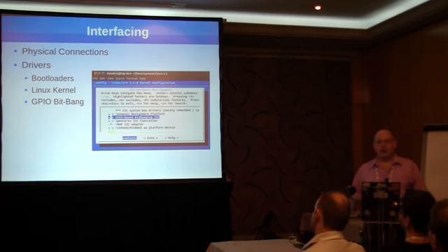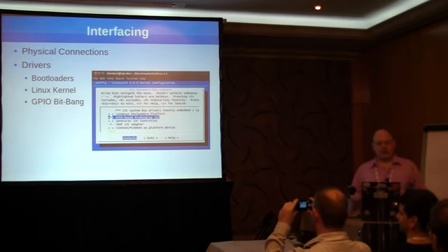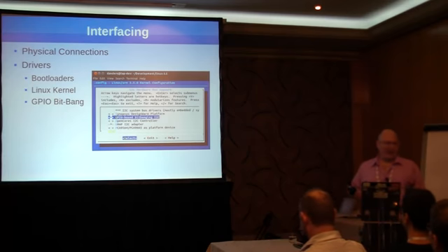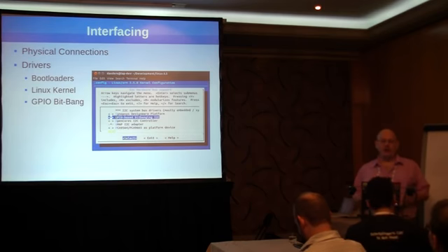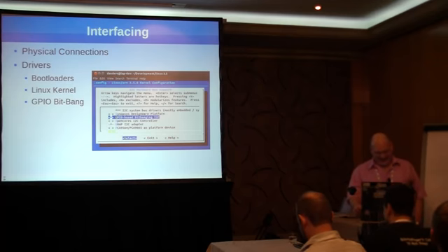This basically only requires you to define 2 GPIOs on your device, and it will actually bitbang I2C for you. Now, I know that everybody in here hates the idea of GPIO bitbanging, but it's actually a great tool for cleaning up mistakes, and we'll get into that shortly.